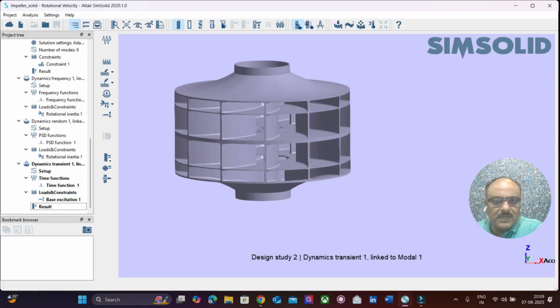So the structure was again modeled, the finite element model was built with the basic considerations, the load considerations, the boundary conditions, etc. So the bolt locations were all constrained by releasing the axial rotations, and then the forced frequency response simulation was performed, and then we extracted a set of 10 frequencies, and we found that a few frequencies were matching with the natural frequencies.